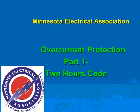The arc flash and arc blast are directly proportional to the amount of short circuit that your power system can inject into your building. So when we talk about protection devices, it's directly related to the proper PPE you gear up with when you work on energized electrical equipment. So big deal, 70E.